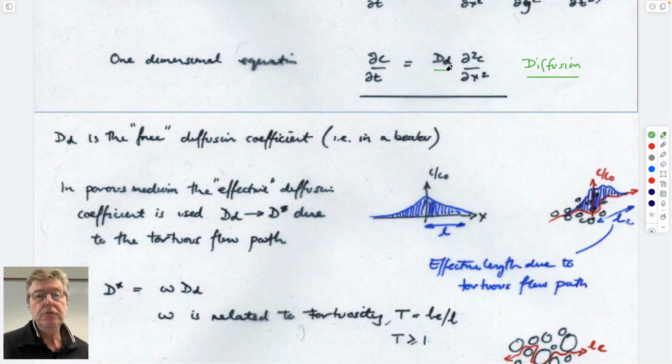If we look at this diffusion, this is the diffusion of my aftershave in an open room which only has air in it, and air is the only carrier. And if the air is stagnant, it's just moving by diffusion. If you fill this room up with sand, so it's an aquifer, then to get that to diffuse towards you, it has to go through the pore throats, and those pore throats only fill up part of the porous medium, just like for advective velocities.